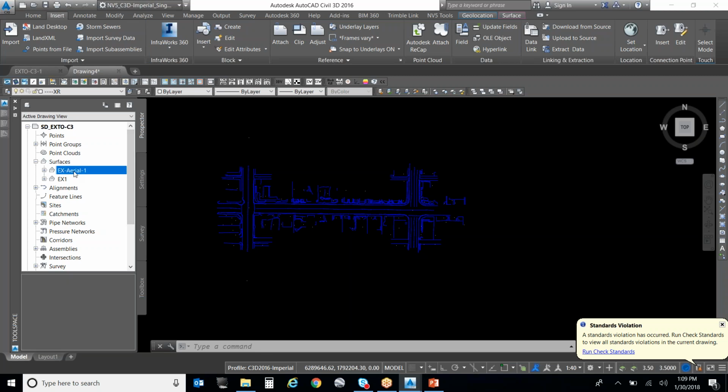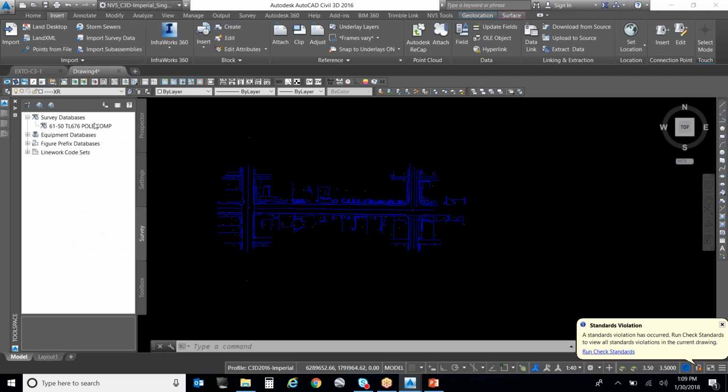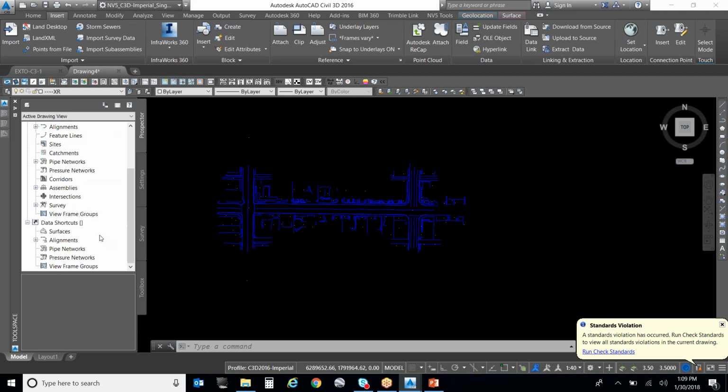And then the third tab down is the Survey tab, which is the location of your survey database. This is where all your survey points and survey figures are stored. When you access this, you should open that survey database as read-only, right? In 99% of circumstances, your survey guys should be adding import events to your survey database and doing their own QA/QC prior to it hitting your desk. So all that information should already be entered into your survey database. So open it as read-only so you're not changing things accidentally, because it's not necessarily part of your workflow. We don't want just anybody in there making global changes.